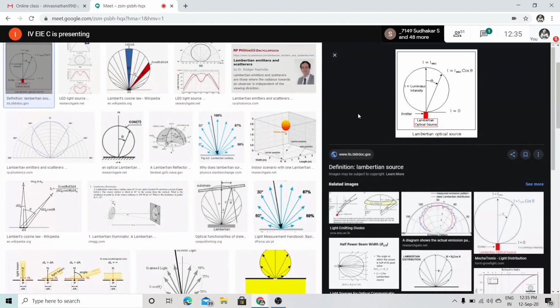So in electro-optic modulators, the applied voltage will change my refractive index directly, whereas in a magneto-optic modulator, we find the change in plane of polarization because of the applied magnetic field, and this change in plane of polarization is related one way or another to the refractive index change.